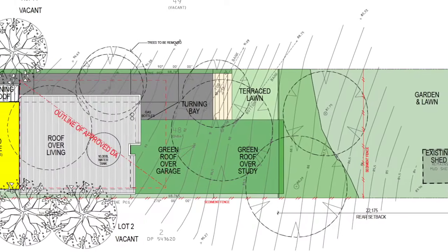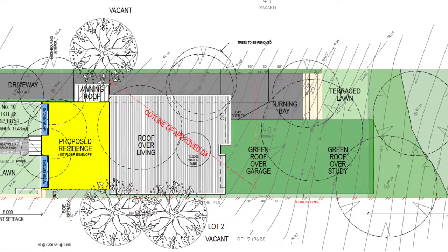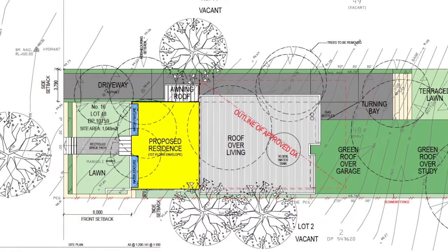We then zoom in a little, and so we're now seeing the whole site. And so this will be the site plan. Now the site plan may also show other information. Most importantly, that's going to show the house on its site, on that block of land. Now, if that block of land is very, very large, we may again need to split this up into two drawings. So we might have a location plan or an overall site plan, and then we might have a detailed site plan.